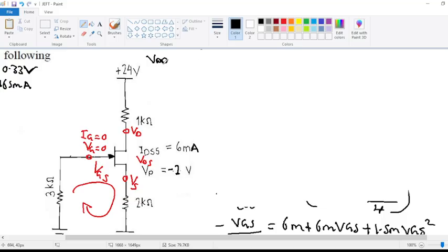So we start with how the current is moving. It's moving in this direction. This is what we are going to follow. So we are going to have our VDD there minus the voltage at this point here. It will be ID, because that's the drain current which is going through this resistor. So we're going to have our ID there. We'll multiply by the RD for us to get the voltage there. Minus, we have the VDS there.